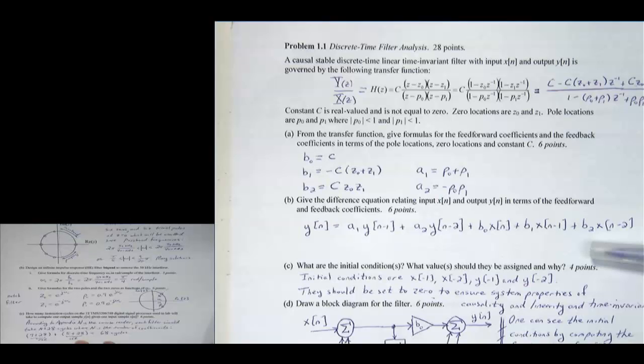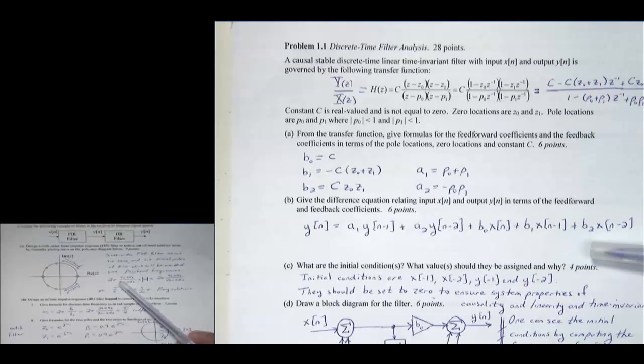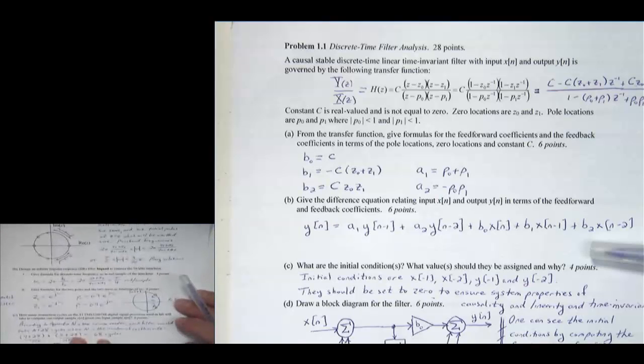And so as long as you can figure out, so for a 6th order, I think where people had some trouble is for a 6th order FIR filter, how many coefficients? 7. That's caught a lot of people. So you didn't lose too many points there. And then for the biquad, there are 5 coefficients, right? There's the 3 feed forward, B0, B1, B2, and the 2 feed back, A1, A2. So there are 5 coefficients.